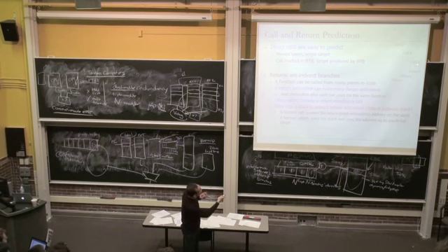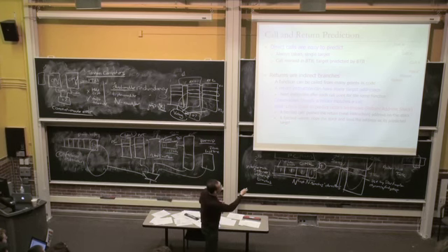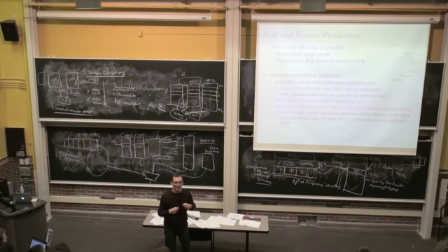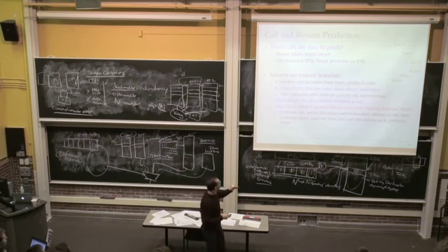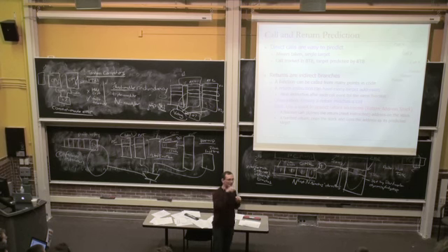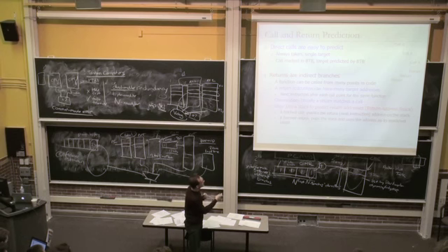So what happens is usually something like this. You have nested calls, and at the very innermost nesting level, you return. And this return corresponds to the innermost call. And the next return corresponds to the next innermost call. And the next return corresponds to the next innermost call. So this looks like a nice stack behavior, right? What you can do is when you do a call, you push the return address on the stack. And when you do a return, you pop the address from that stack and use that as your prediction. That's the idea of a call return stack. Use a stack to predict the return addresses.